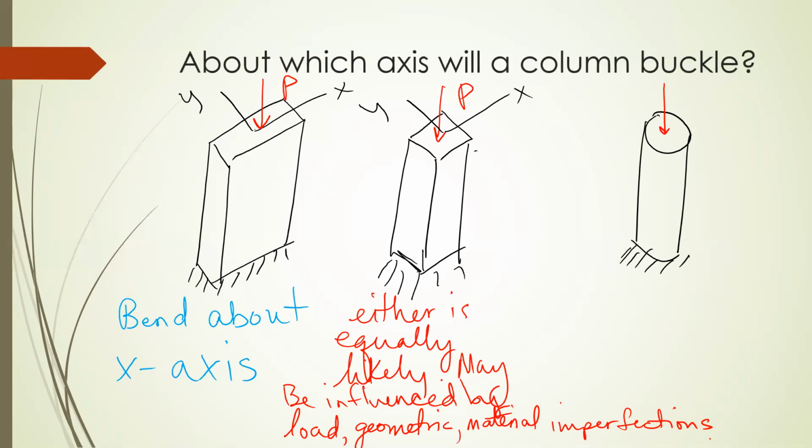And so as you're going to see in our coverage of buckling, in order to determine the load at which it deflects, we have to actively choose to make it deflect. We have to assume that it did deflect. You can't directly calculate the load because there's always an option that says, I stay straight. And so you can never really get to that answer directly. You have to choose that you went down that road and then backtrack the load that caused you to end up there. Good, that's a really important theoretical point.